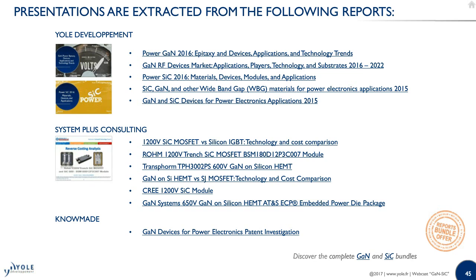Okay, thank you very much, Hong. Elena, the first question would be, what are the main cost drivers for silicon carbide and gallium nitride? As concerns silicon carbide, we consider the main driver to be the substrate cost, and connected to that the relatively small wafer size with respect to silicon. And as concerns gallium nitride, it's the epitaxy, so the cost of the epitaxy and the manufacturing yield.